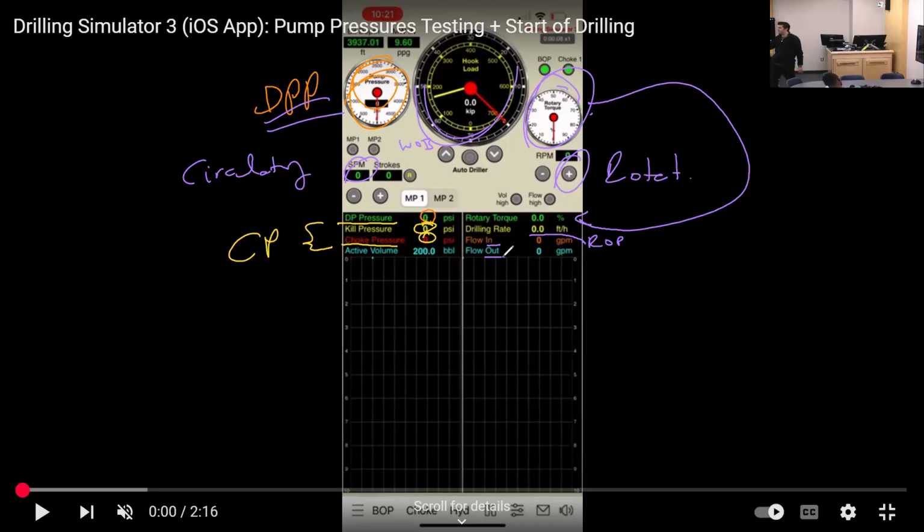Okay, what if I'm pumping at 100 and I'm getting 140? Something else is coming into my well. Then I need to be very, very careful. And you understand if I lose circulation, it will eventually become a kick. So I need to be worried anyway.